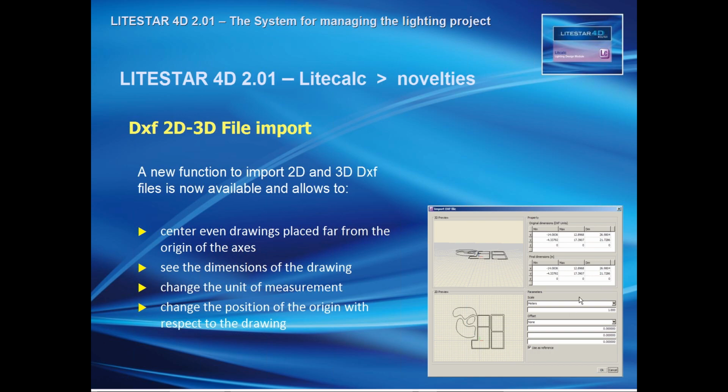It is then also possible to visualize the unit. As you probably know, the DXF files do not bring the unit information. So it is necessary to convert the DXF units into meters. Meters is the unit used by the program. In this window you have X, Y, and Z that for a 2D file is always equal to 0. So we focus on the first two.